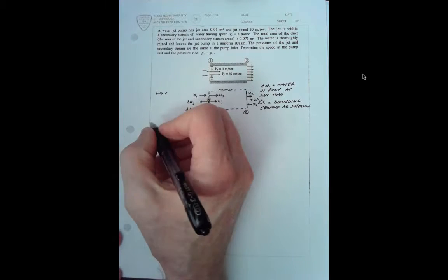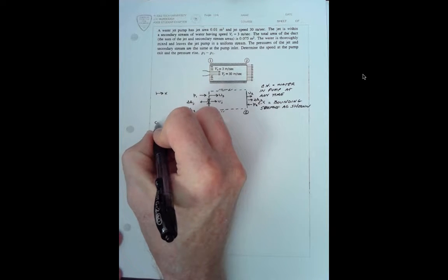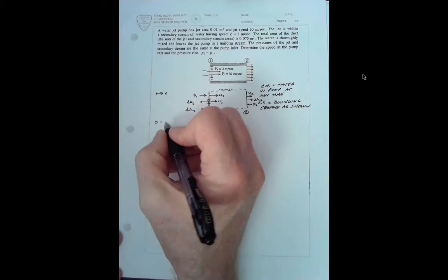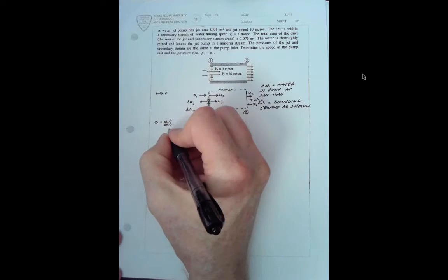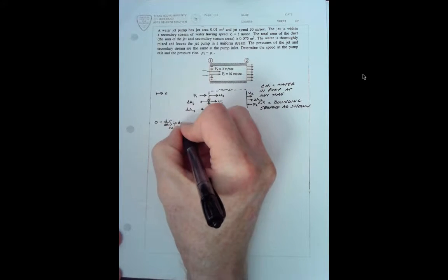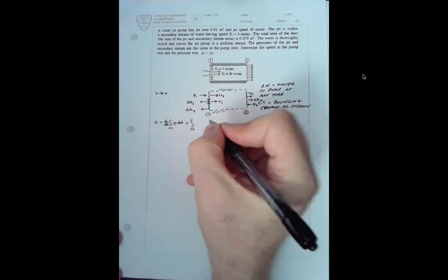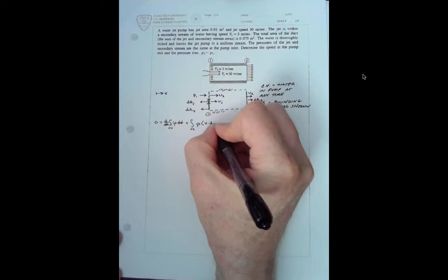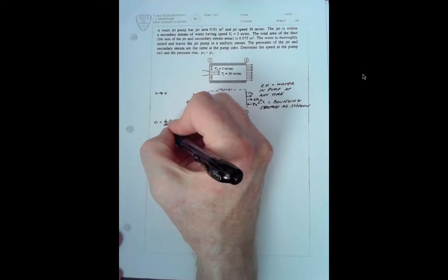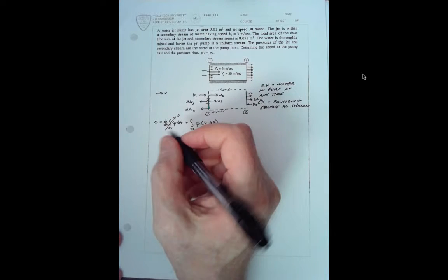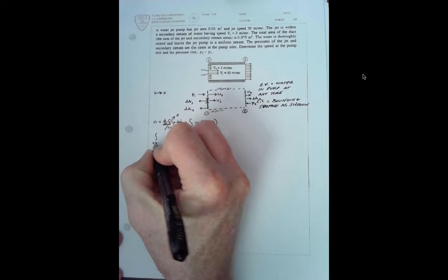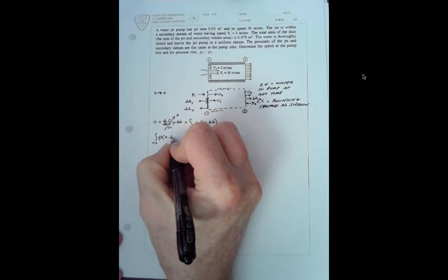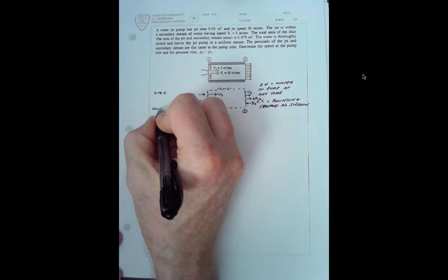So our solution is to apply continuity. So when we're using momentum, we'll almost always have to apply continuity also. d by dt integral over the control volume of rho d volume plus the integral over the control surface of rho v dot dA. That will zero out because the control volume is known to be fixed in size. So all that we have left is the integral over the control surface of rho v dot dA. So this is continuity.